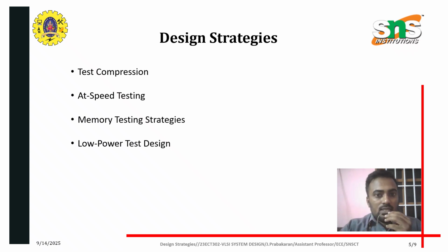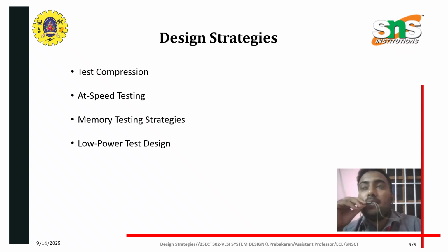And the last thing is low power test design. Test may cause excessive switching, leading to overheating and false failures. So we follow some strategies like power-aware ATPG.